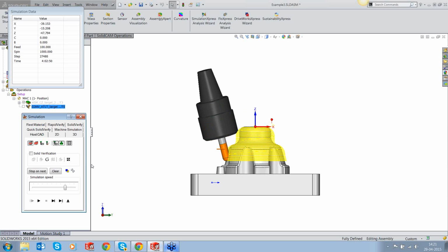Right, so you can see that it was pretty easy and very powerful. It can just pick a 3-axis HSM toolpath, and depending on the holder geometry and the tool length out of the holder, it can immediately convert an HSM toolpath to 5-axis and give you, most importantly, a collision-free 5-axis toolpath, which is very, very important.